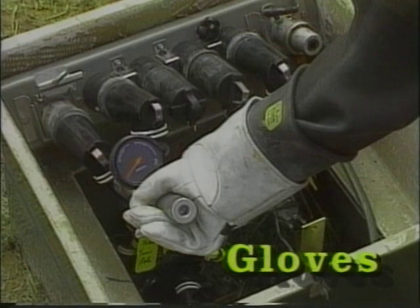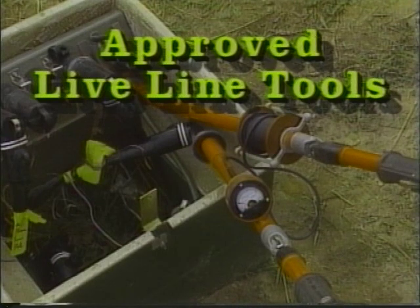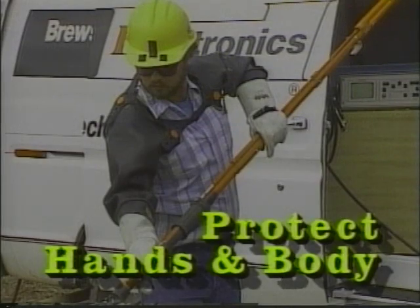Some of the absolute safety rules are the use of high voltage rubber gloves. These gloves shall be worn by everyone that will be working inside the transformer enclosure and during hookup, operating, and disconnecting of any high voltage test set. Approved live line tools shall be used for all shorting, grounding, and connections being made. Bare hand or body contact shall not be made to the test set or cable under test until the test set is de-energized and all parts of the circuit are grounded.